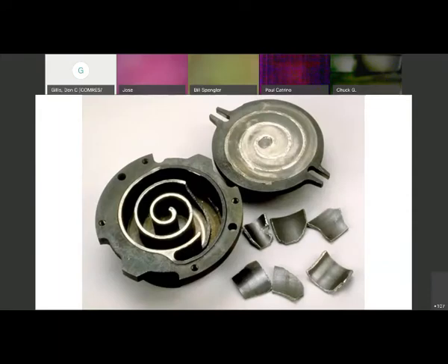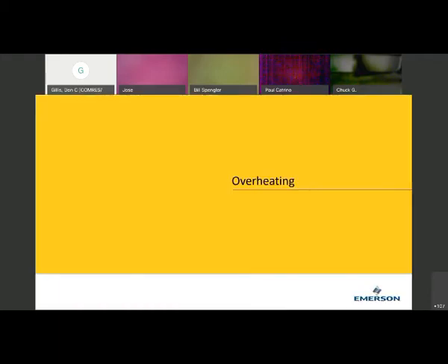As we can see. And I only put a few pictures in here, but this just shows you a scroll. This is the bottom scroll section that's referred to as the orbiting scroll. This is the fixed scroll. This is actually upside down. This should be setting on top of here. This actually has flanks and tips just like this does. Obviously that broke all the way off. So even as good as our scroll compressors are, at one point, they're going to bust some parts, okay? They'll tolerate a little bit, but not that much.